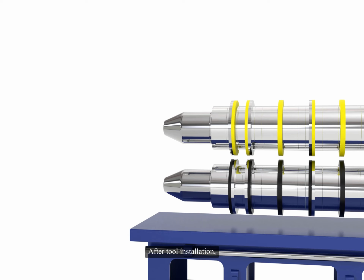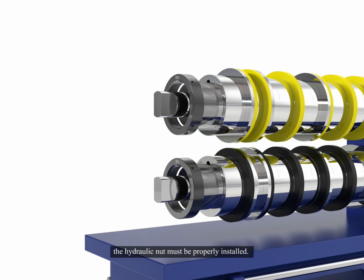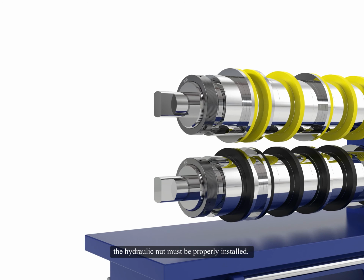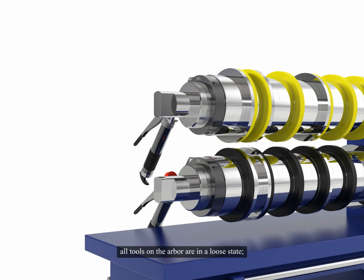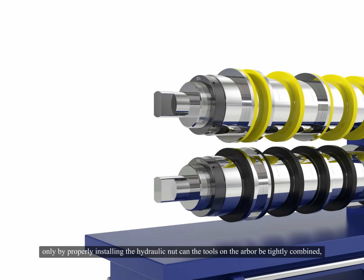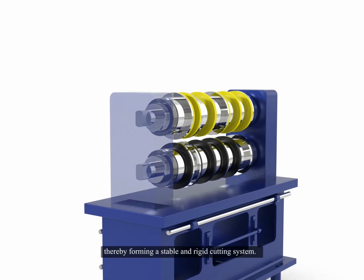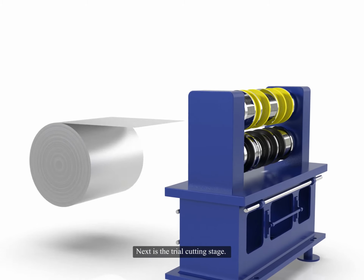After tool installation, a comprehensive and detailed inspection must be conducted, focusing on checking for any errors. After confirming no issues in the inspection, the hydraulic nut must be properly installed. It should be noted that before installing the hydraulic nut, all tools on the arbor are in a loose state. Only by properly installing the hydraulic nut can the tools on the arbor be tightly combined, thereby forming a stable and rigid cutting system. Next is the trial cutting stage.